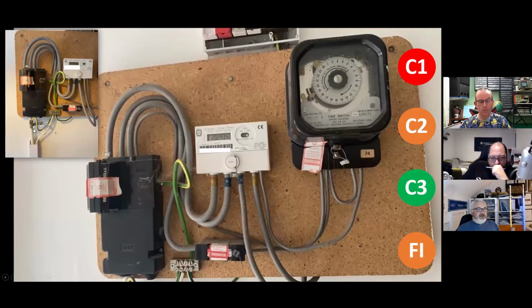But yeah, so what do we think? Do we think it's a TN-S? Do we think it's a PME? What do we declare it as? Well, as a couple of people have suggested, maybe testing each one to see what you got, because the polling has picked up an FI on this. That's a good one. And I would actually say on the polling, it's an FI. 62% FI. So, yeah, no PME label.